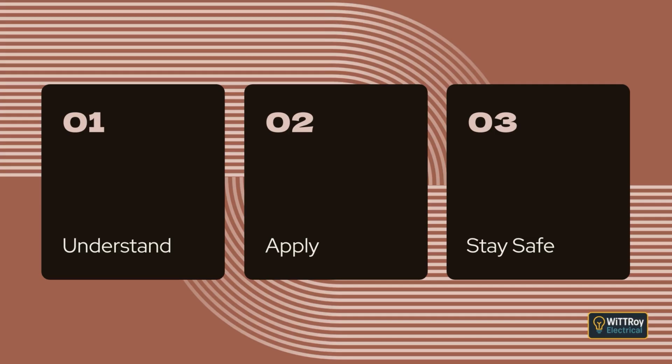Where wiring is installed in places with explosive gas or explosive dust, the wiring system must meet the special rules for hazardous locations. The wiring must be chosen and installed to prevent ignition risks and must meet the requirements of Clause 7.7. Clause 3.4 Current carrying capacity.